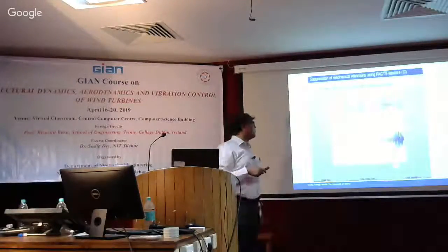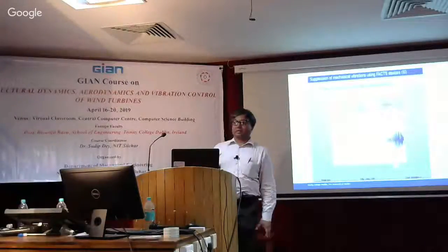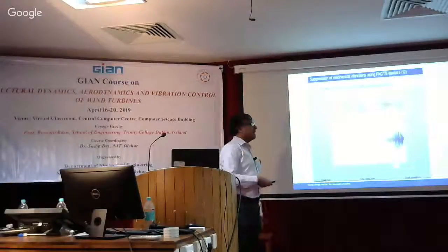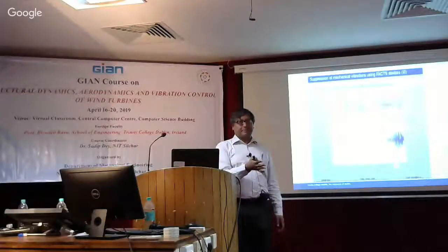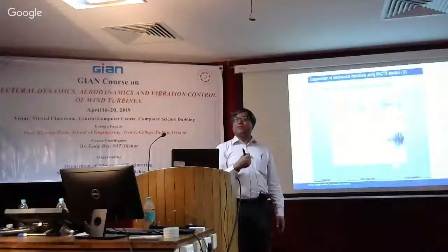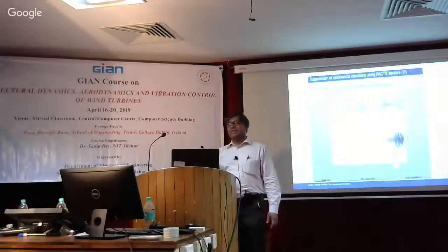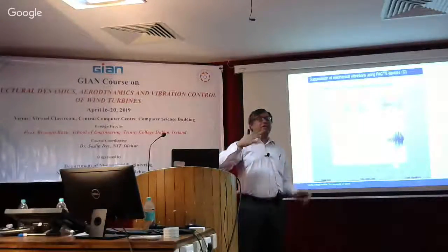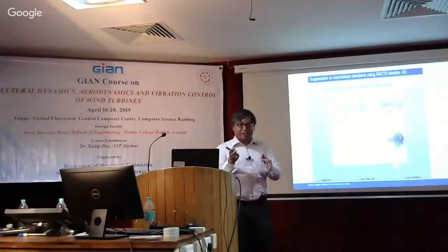The other situation could be, if you have a case where your mechanical sensors send some accelerations or displacement, and you do an emergency shutdown of the plant. And obviously, then you have to be disconnected from the power grid. But again, the grid code says that you have to be connected to the grid for a certain amount of time. And if you don't, then you have to give a penalty. So there's a financial implication to that.